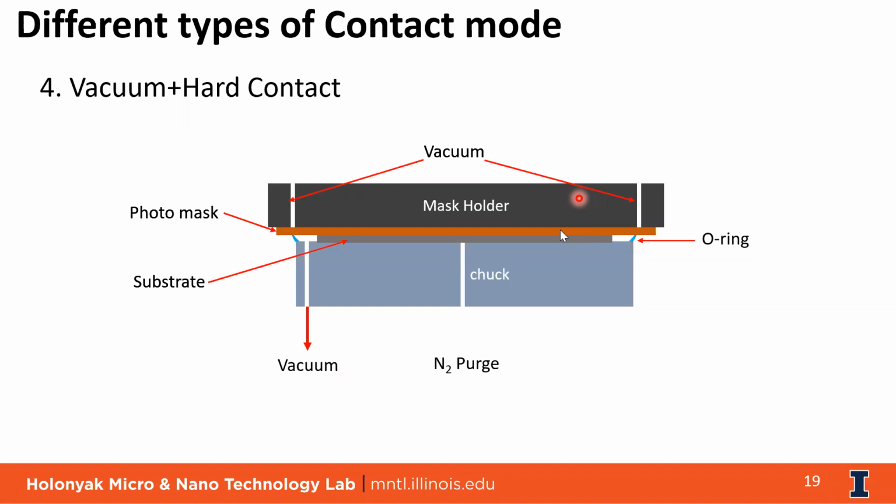Okay. So the difference between using a transparent substrate and silicon. Silicon, when you expose it, absorbs your UV. There is something called backside reflection, and you won't get any backside reflection in silicon. But when you use a transparent substrate, you will get backside reflection since both surfaces are smooth, which can unintentionally expose the whole wafer. So that's why you always find variation between a silicon substrate versus a transparent substrate.